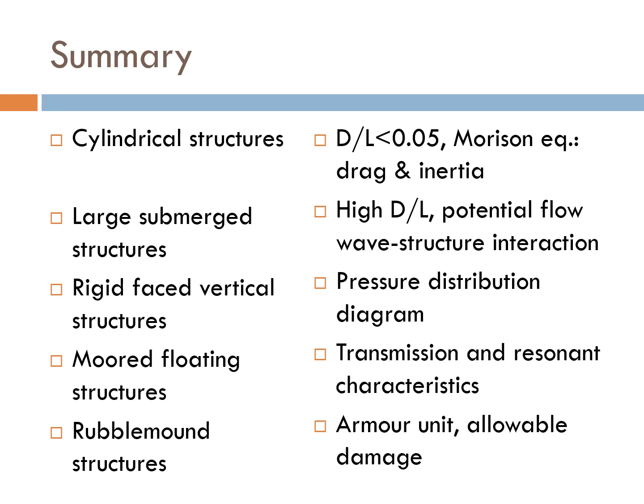Also, floating structures will require detailed investigation into their resonance characteristics to ensure that they do not become vulnerable to sudden damage. For rubble mound type structures, the design is principally governed by the type of armor unit and the weight that is required for the given coastal climate, and also the allowable damage that is adopted for the design.